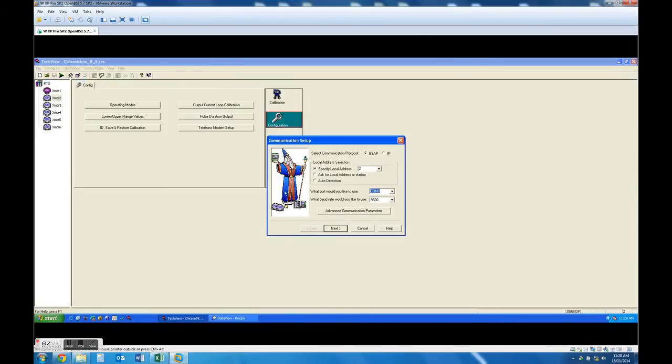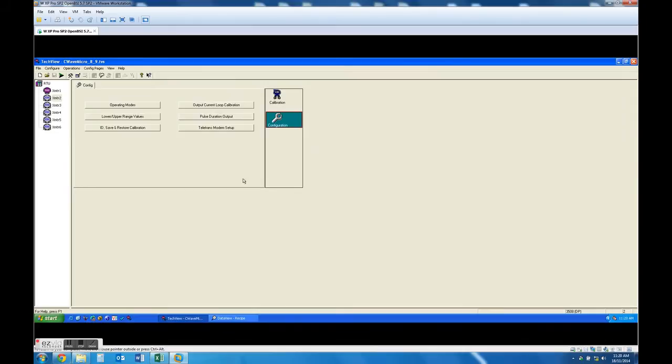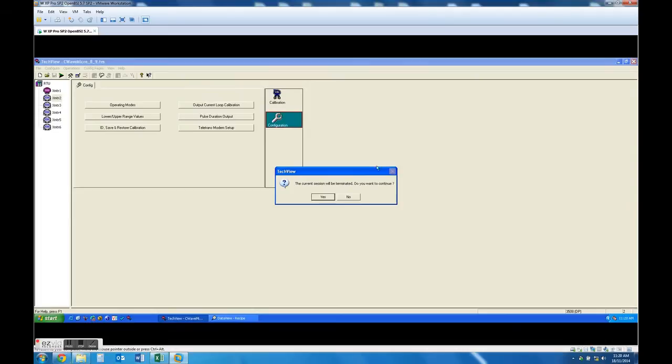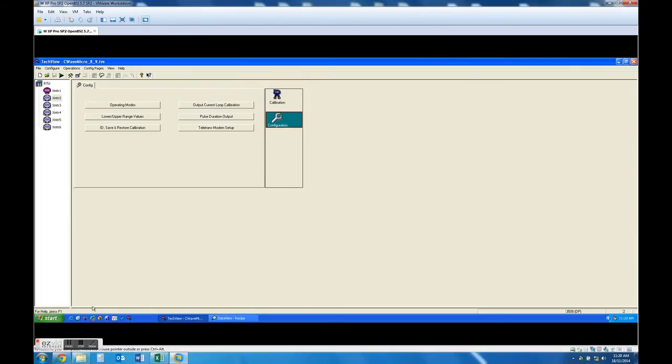You can also change the local address / group number of the controller with the configuration wizard, much like LocalView. You can also write user notes to the controller's audit trail, access / modify parameters stored in the flash memory of the controller, and start other OpenBSI programs or utilities to perform other activities. Note, only one TechView session can be activated at any given time.